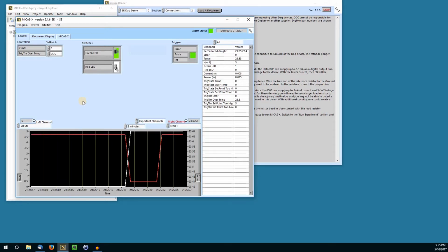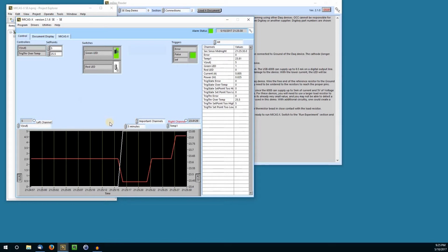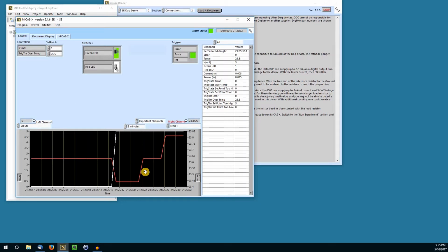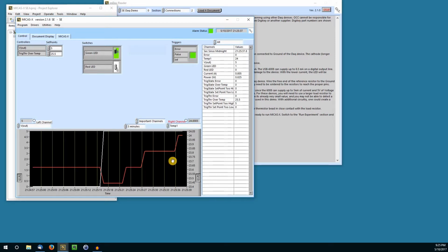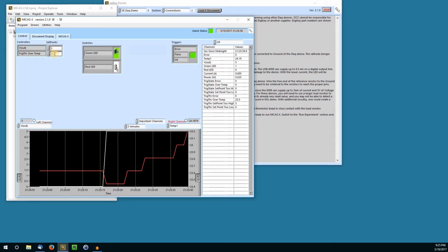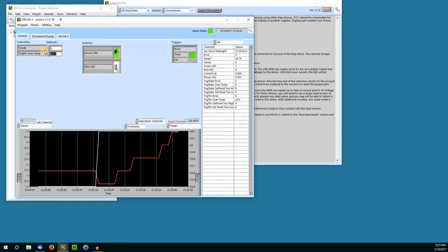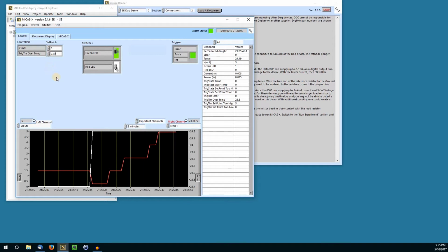When the temperature has leveled off, use the graph to find the temperature halfway between the lower and upper levels. Enter this value in the trigger threshold over temp controller channel. This tunes your system so that the green and red LEDs will indicate whether the temperature is above or below the threshold. Continue adjusting the voltage to verify the operation of the system.